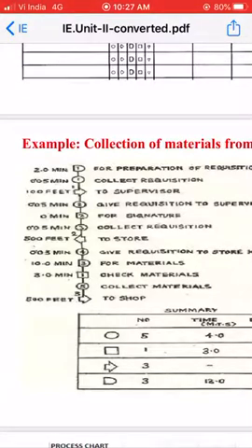Then we need to carry this requirement sheet to the supervisor. So this activity is represented by the symbol arrow, that is transportation. Here this activity represents a transportation activity. So third activity is transportation activity. So on the right hand side we have written to supervisor, on left hand side we have written 100 feet